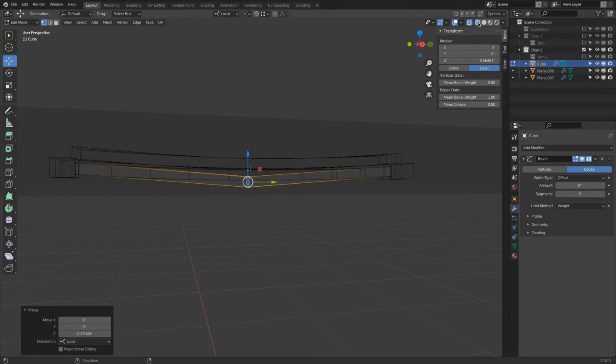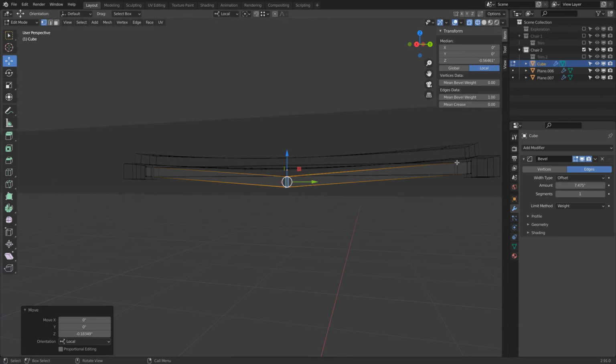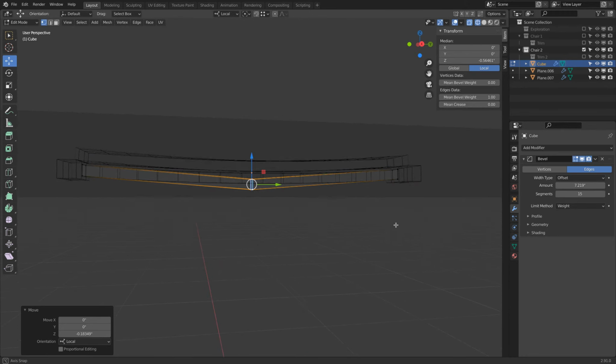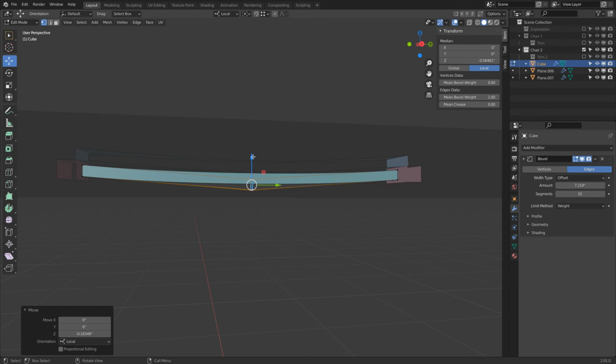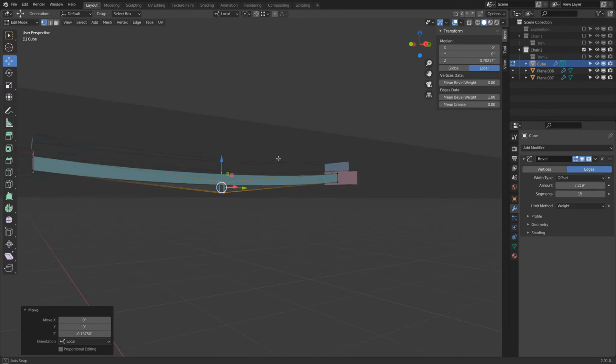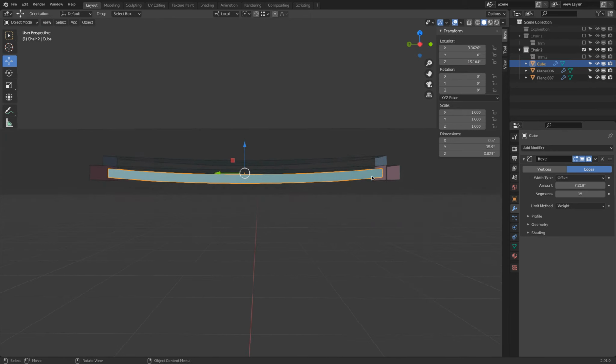And sometimes here with one, then there I can see where's actually the end of my rounding. It's right there and there. And then I can add more into it. This looks good. Okay. When this would be bent, ideally this would be a circular bend, and the fillet is a great tool to make a circular bend.